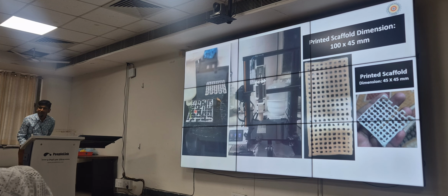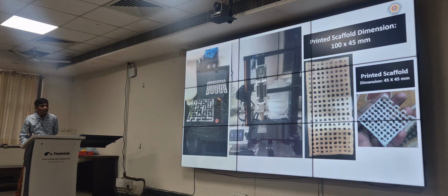And what was the problem? The problem was that the composition you had made did not have good viscosity. It was not homogeneous. And thirdly, since it was not homogeneous, from time to time the nozzle was blocked. Right? Fourth, it was not making layer by layer. Before it made another layer, it was still in liquid form. So the structures were completely disturbed and distorted. Right? When slowly all these problems were resolved, ultimately we were able to get nicely printed structures.